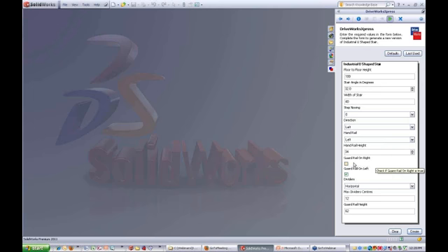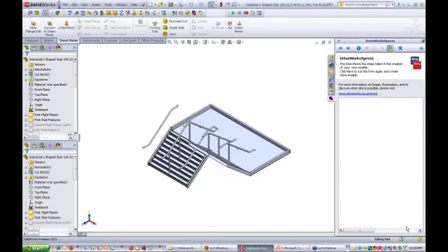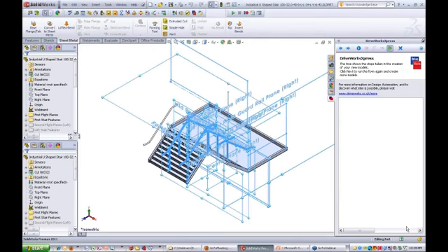We don't want a guardrail on the right, we do want one on the left. We'll change it to vertical this time, we'll make it a lot smaller, and smaller again. So different values. If we create that, then we'll get much narrower stairs with only a single handrail going up to the left instead of the right.